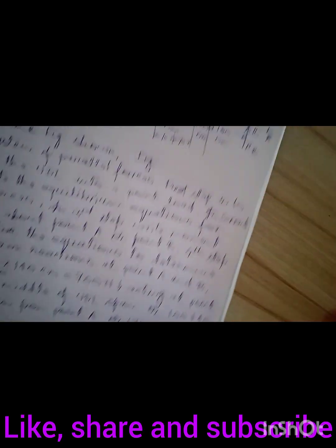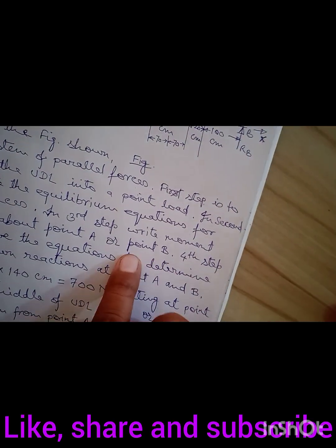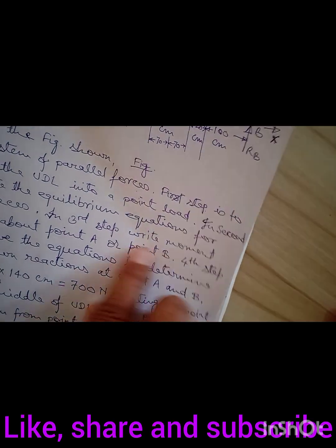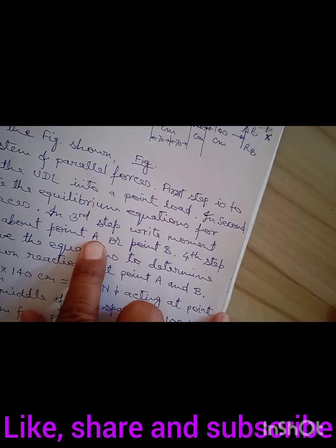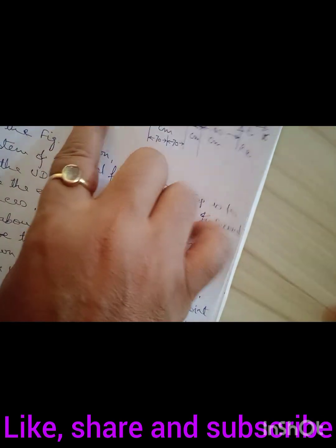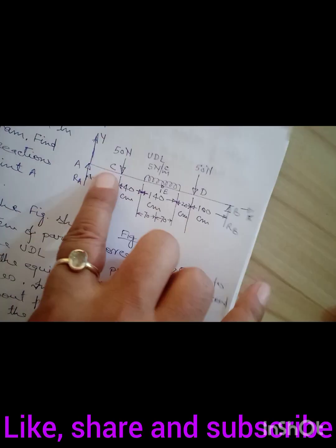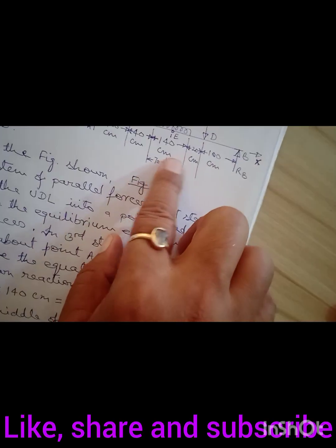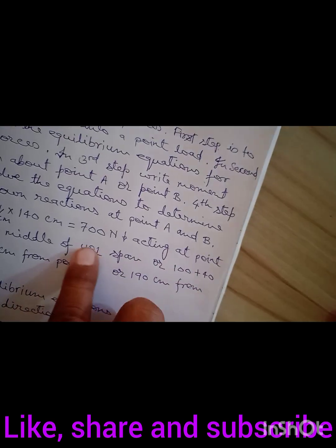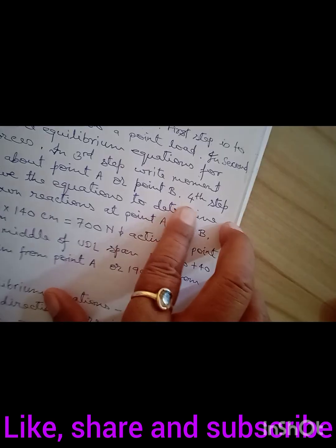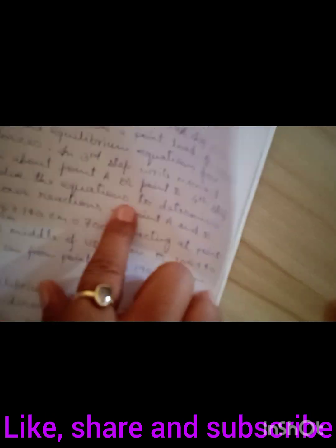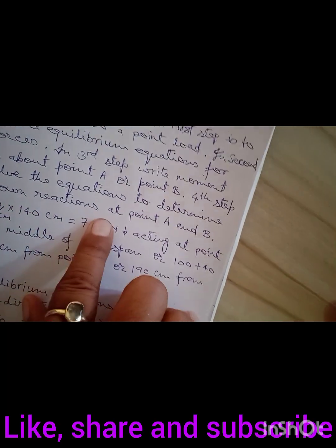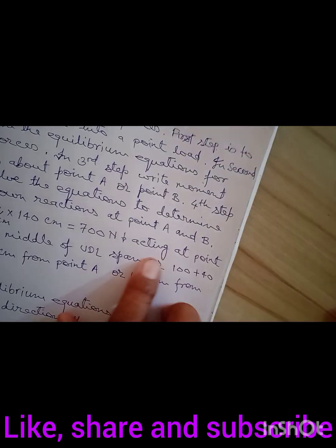This is the second step, we will discuss it later. In the third step, write the moment equation about point A: we will write the moments of forces and their sum. And the fourth step is to solve the equations and determine the unknown reactions at points A and B.